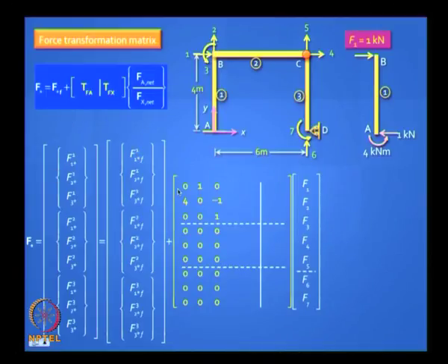Axial force. Will there be any axial force in this element? No, that is why I put 0 there. The second item corresponds to the moment at this end; it depends on how you put your element, but it's 4 here, right? And the third one, the moment at B, is 0, right? It depends on start node, end node. I put the start node at A, so anticlockwise is clear, so it's 4.